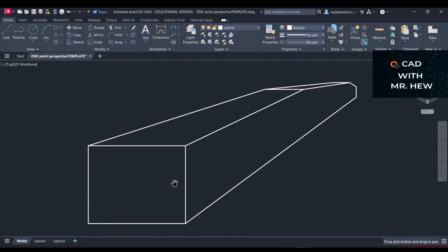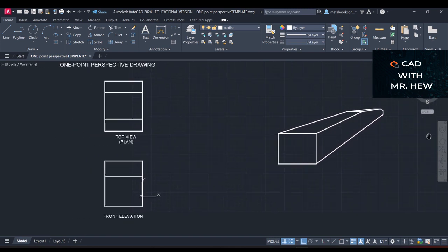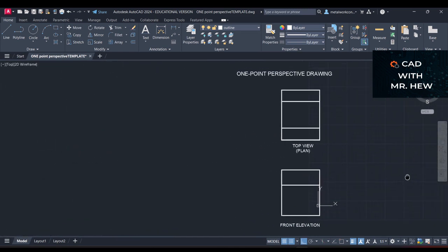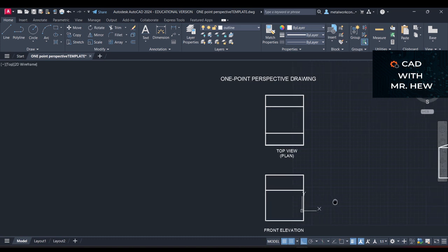For those who are just joining, I gave the persons who were here before you a challenge to draw this two-dimensional view represented by the top view and the front elevation. The top view is the aerial view looking down. So if you're in an aeroplane in the sky looking down, you would see the house top. So the top view is called the plan. And the front view, if you're standing on the road looking at a house, that would be the front elevation.